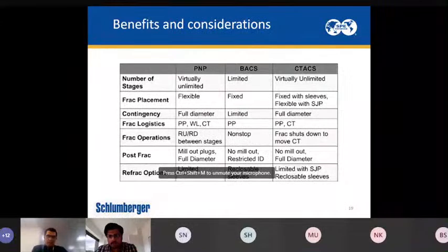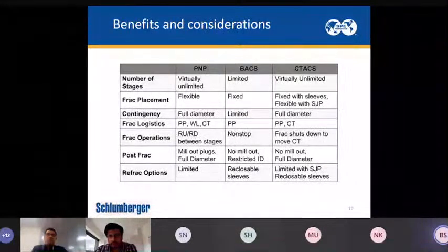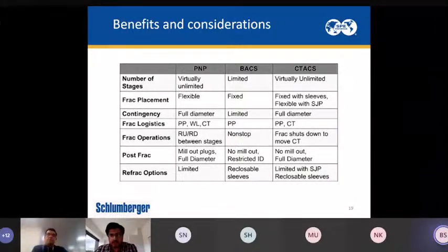Thank you. So depending on the well fluid and well conditions, we have to decide which kind of diverter we are going to use chemically. Yes, temperature, pressures and the reservoir conditions. We need to decide which pill material we are going to use in that case.